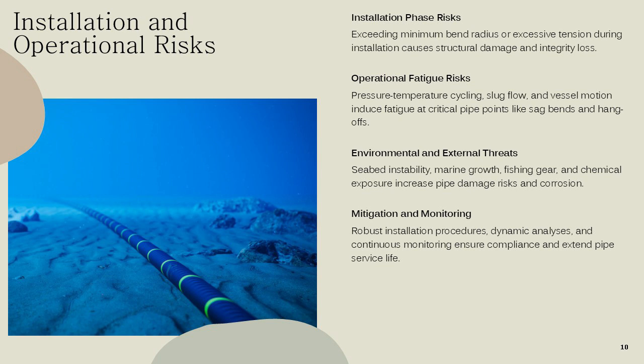Operational risks include pressure-temperature cycling, slug flow, and vessel motions, which induce fatigue and increase curvature at critical points like sag bends and hang-offs. External interference from fishing gear or dropped objects adds further complexity. Environmental factors such as seabed instability and marine growth can alter load distributions, while chemical exposure accelerates polymer aging and corrosion of metallic layers.